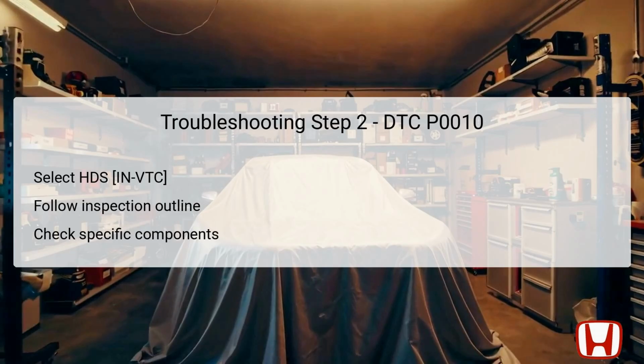In this second troubleshooting step, the Honda Diagnostic System, HDS, should be utilized to select the VTC option. This software provides advanced diagnostic capabilities for reviewing the performance of the VTC system. Using HDS, technicians can view data related to the variable valve timing operation and assess its status based on the parameters set by the manufacturer. It is crucial to follow the inspection outline to ensure that targets are met and abnormalities are clearly identified during this process.